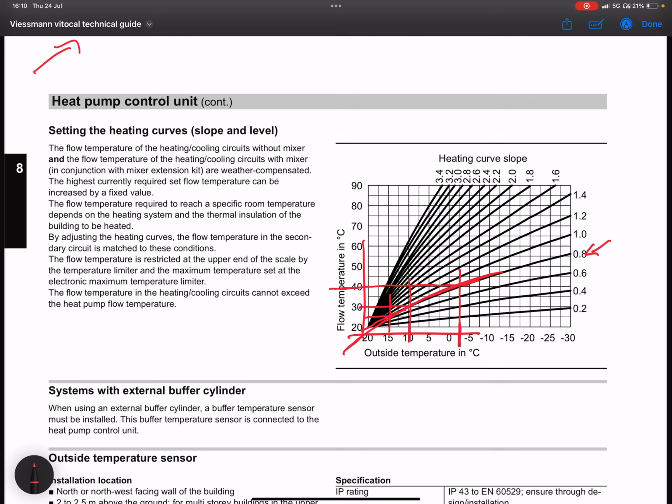And if you have a Viessmann weather compensation, you have a bit more of an advanced control. The steps you get are smaller for more fine control, and you can adjust the level as well. So this is for our design temperature down here at -2.5.